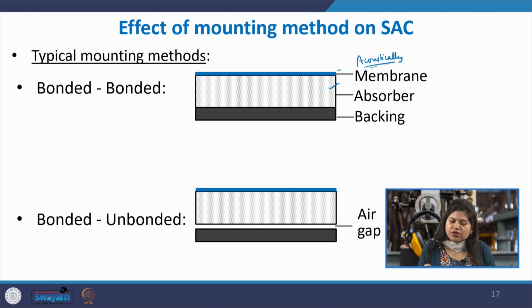In the last lecture I told you what a typical sound absorbing treatment looks like. On top of the material, sometimes you have an acoustically transparent membrane such as a mylar film. What happens? It stops the entry of dust and smoke particles, so that the pores do not get clogged and remain free, but it allows the sound waves to pass through. That is why we have this protective layer of film on top, so that dust, smoke particles and impurities do not clog the pores, and only sound waves can pass through it. There are various such acoustically transparent films.